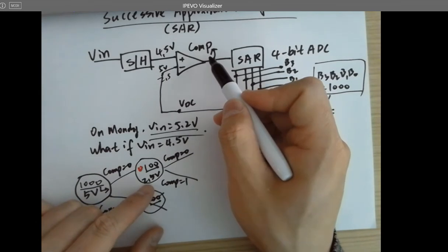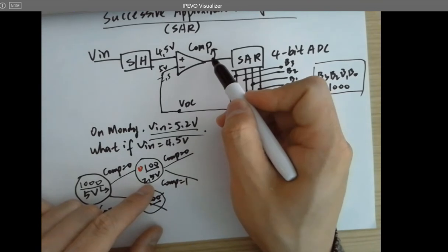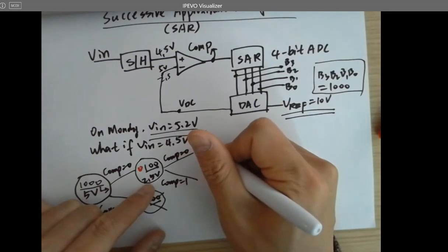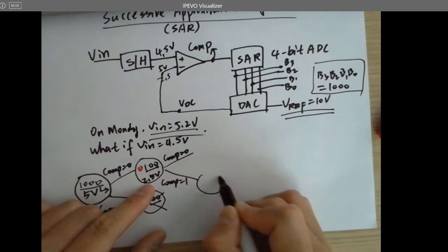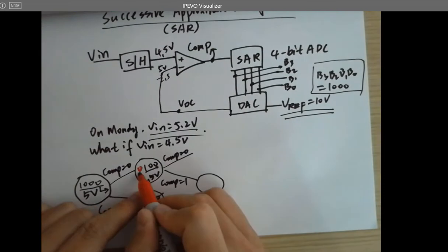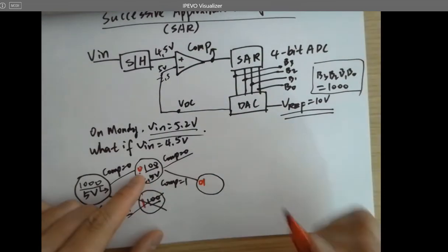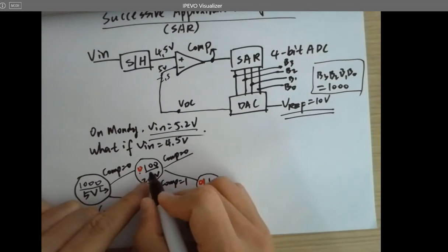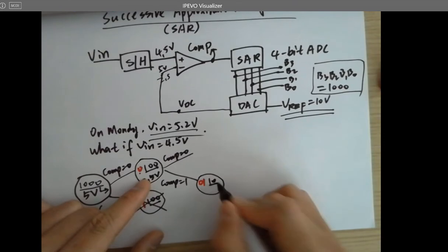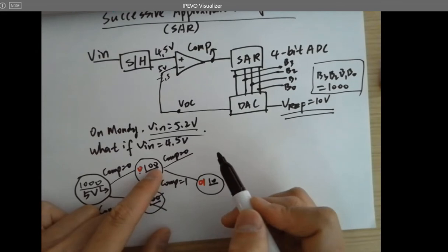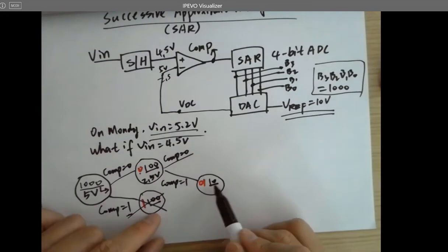Five volts, right? Or 1. So we're talking about digital signals, right? So we got a 1. It actually follows this track. If it is a 1, you just keep the previous MSB and plug 1 after it, and then keep all the other bits, shifting everything to the right. So you have 1, 0 left, and the LSB over here has been shifted out. So it's nowhere. Only 1, 0 left.